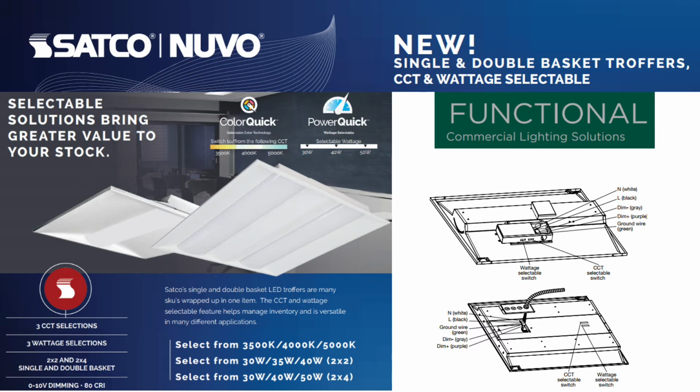Because if you pick a 30 watt design and then decide, well, the customer really wants a 50, certainly you can do it and give them higher foot candle levels, but whatever you calculated for power would not be correct. In this advanced style color quick and power quick fixture, the EM option is not available integrated into the fixture, but you can add a separate emergency backup to the fixture. We have other fixtures of this type, but they're not color and power quick that do have the emergency battery backup built in.